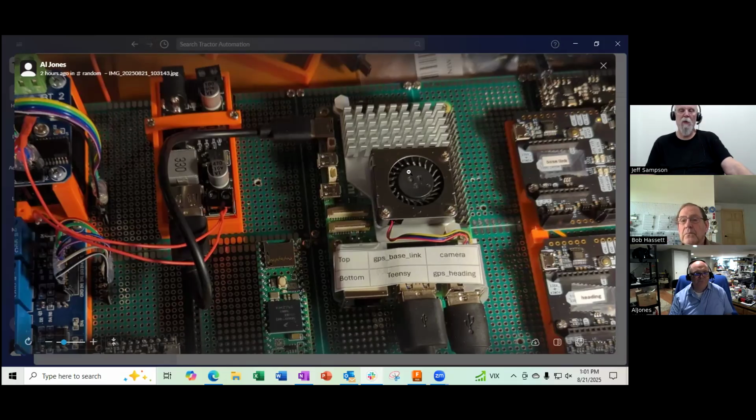I was thinking the main one will come up as you're trying to boot the computer. And if it goes out and says, oh, you don't have a 5 amp power supply, because it does that negotiation, there's just a one-time message that'll come up as you're booting. So at some time right after you booted it up, go out and look at dmesg and search back through for your power messages and see if it says something there. Because theoretically, you should be getting that message every time, unless you've gone into your bashrc or somewhere and said, tell it to ignore the 5 amp warning or something. It seems like it should always complain, but I don't know. That's just some other thoughts that, sometime if you want to look at stuff, you could look at that.